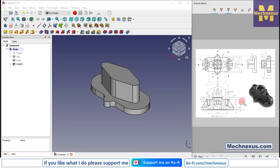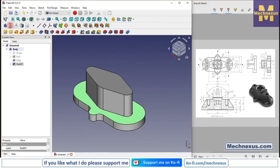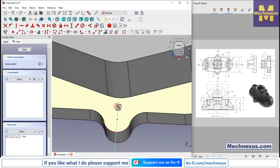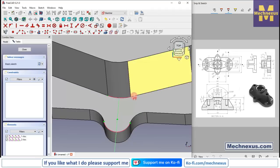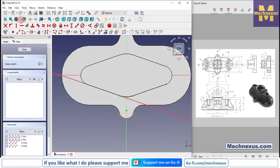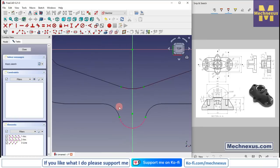And now we will create these two bars. For this we will select this face and click on the sketch, and we will use the project geometry, and we will project it, and we will select this edge and this edge and this edge, and we will switch to the top view, and from here we will switch to the wireframe. We will delete it.